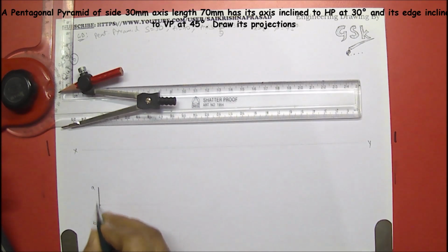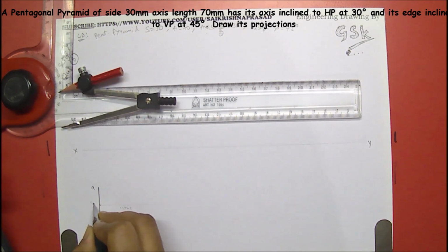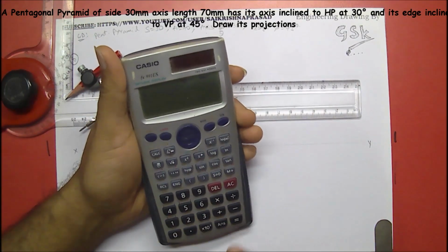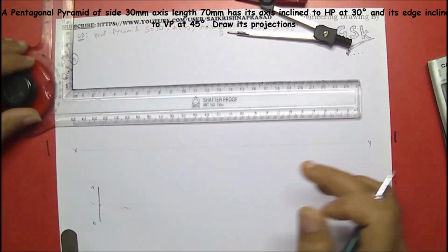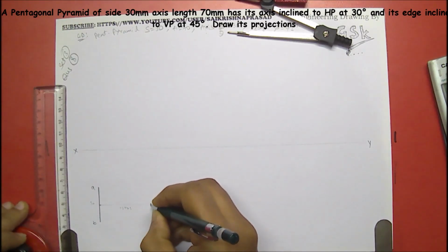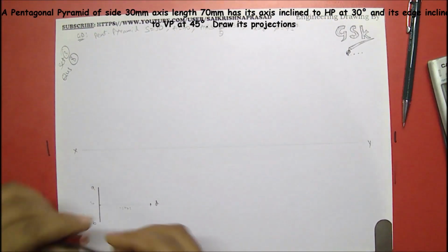From the midpoint of AB, just draw the perpendicular line and measure this distance as 1.54 times S. S is 30 over here, the side, means 1.54 times 30 would become 46.2. Just take a point 46.2 over here, means this point would become D,